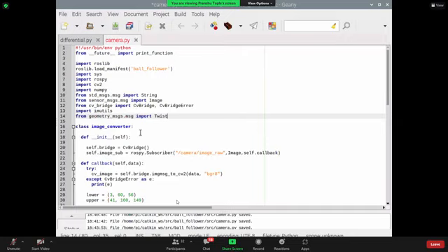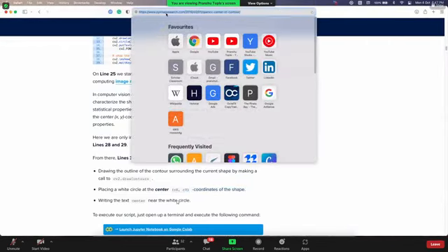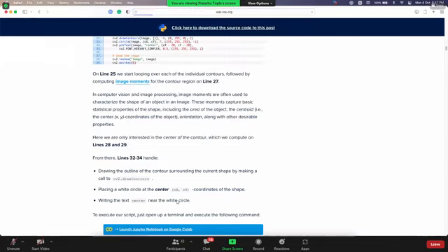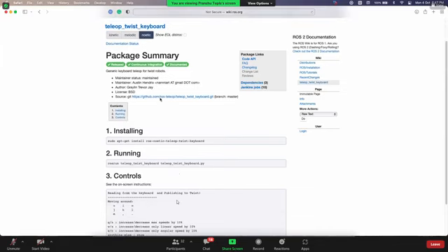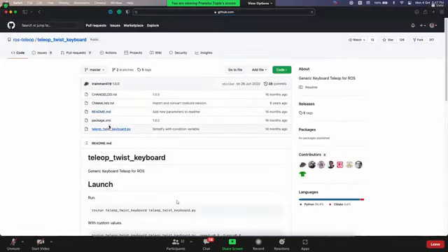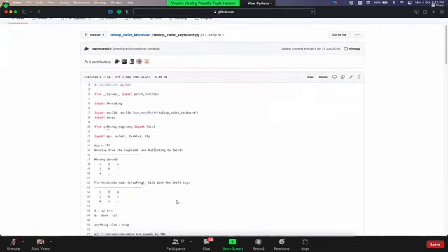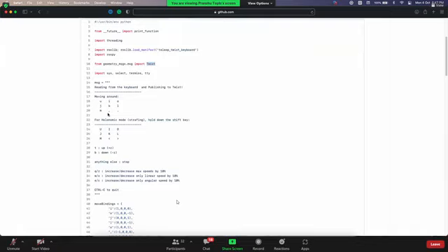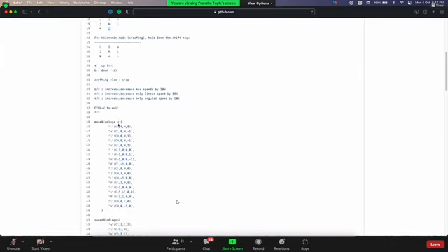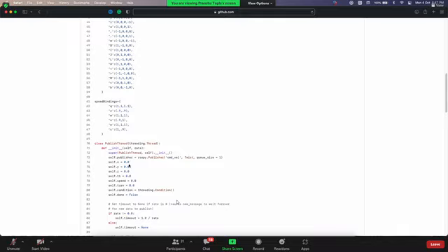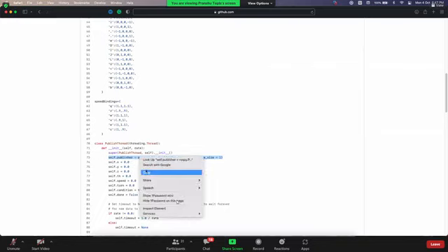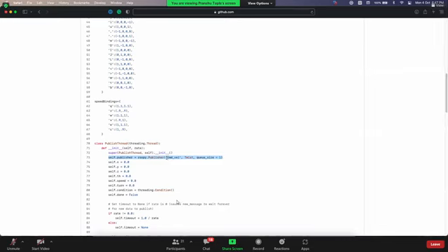Okay, now to publish geometric messages, we were using a script called teleop twist keyboard. Teleop twist keyboard. Okay, if you go on to their GitHub, you will find this Python script which runs, and here they are publishing these geometric messages. Okay, so now whenever I press I, it goes forward. For J and L, it moves left and right. So let's see where it actually works. So first, it starts a publisher. So now let's start a publisher for ourselves for the command velocity.